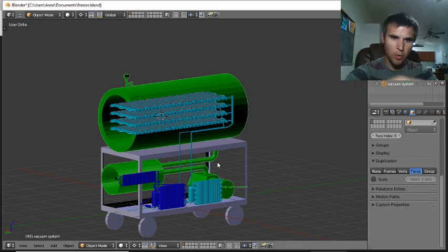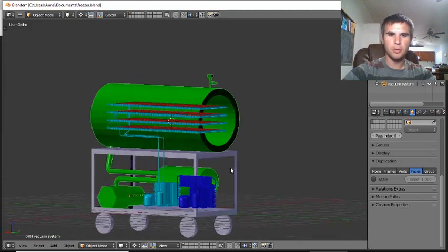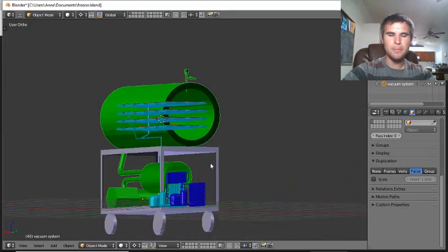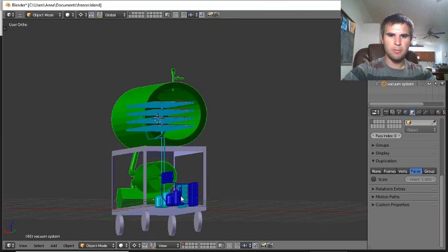And then obviously as the pressure drops, it becomes much more difficult to actually get the material up in the product chamber to actually move down the pipe. And as it does, all the resistance it encounters will actually hugely affect our ability to pull the vacuum. That being said, I was looking at the triple points, and I was looking at the pressures. We don't really need to or want to pull a huge vacuum. We want to pull deeper probably than Wayland's machine is, but it doesn't need to be crazy.